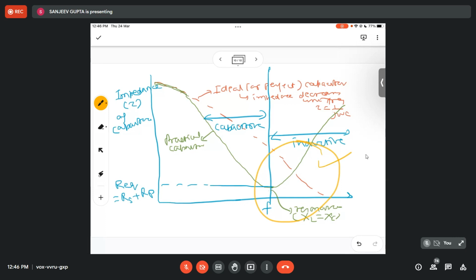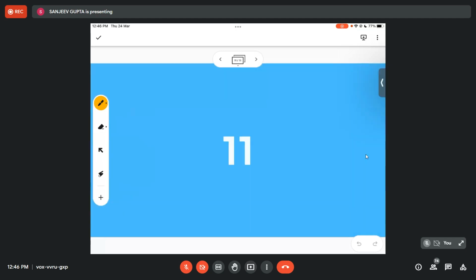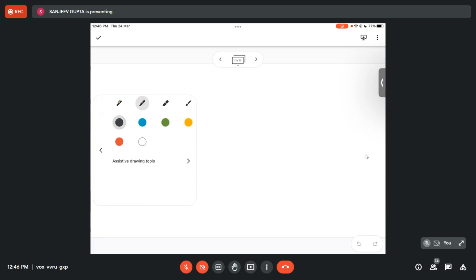The whole thing has actually changed, the whole world has changed. Okay, your capacitor, which we used to think of as a capacitor, is not behaving like a capacitor also. At least up to a certain frequency before the resonance, which could be a few megahertz, it will behave like a capacitor. But after that, in today's frequency of interest, it may behave like an inductor. Totally different behavior.